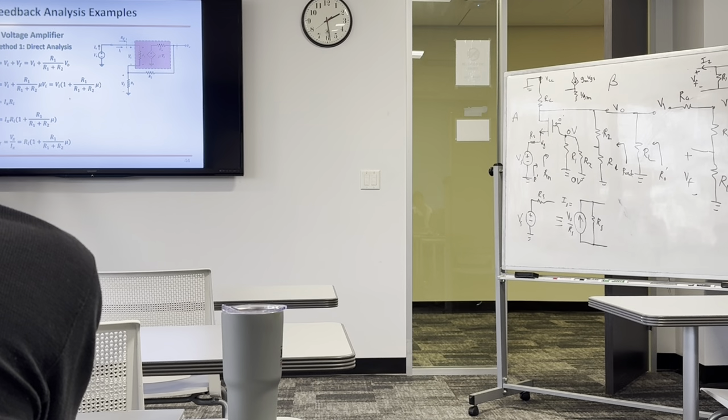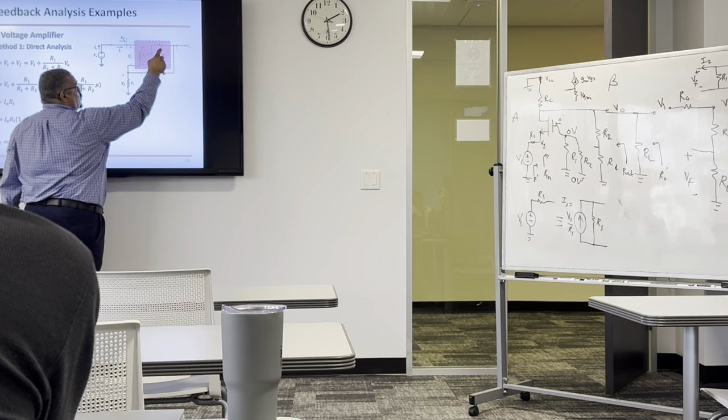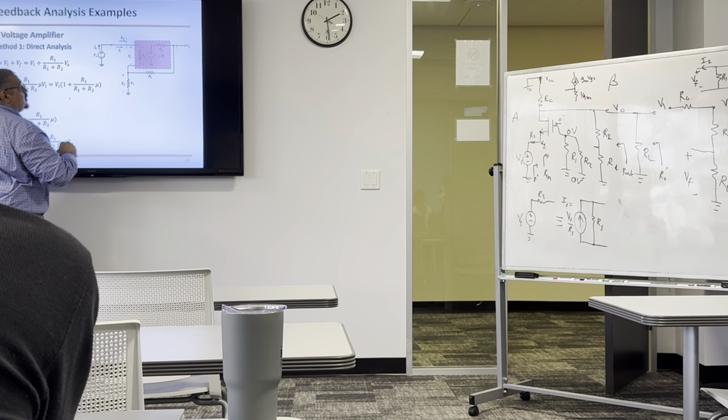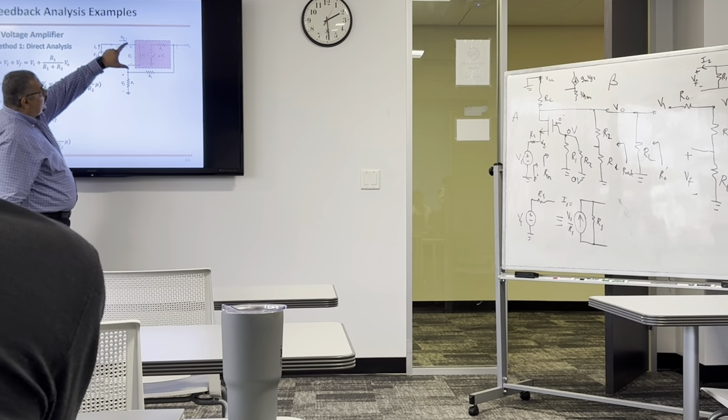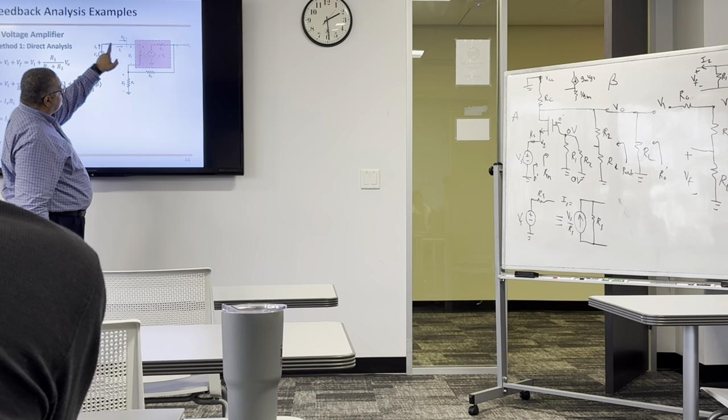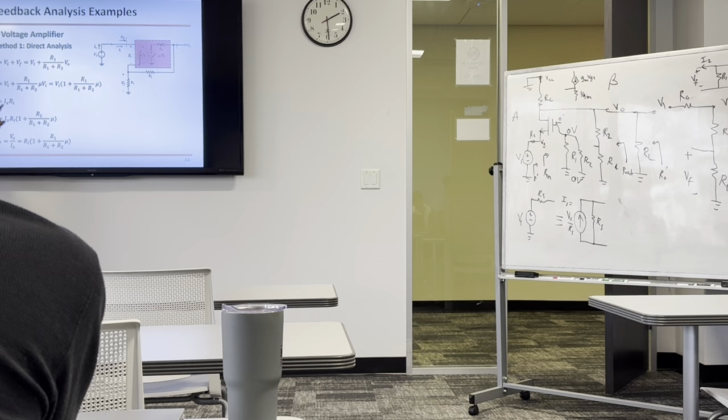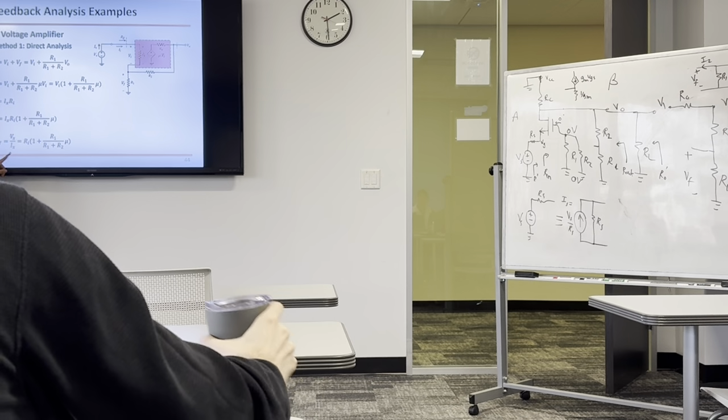It's not a function of Ix. We need to get rid of this and this to make it a function of Ix. Well, we know that V out, if RO is very small compared to the series connection of these two, is going to be the same as this one. So V out is mu Vi. We take Vi common. All we need is to find Vi in terms of Ix. If you look at this, Vi is the same as Ix times Ri. So Vi is Ix times Ri. We take this and substitute it here. Now we have an equation that links Vx and Ix. We solve for Vx over Ix. This gives you this.